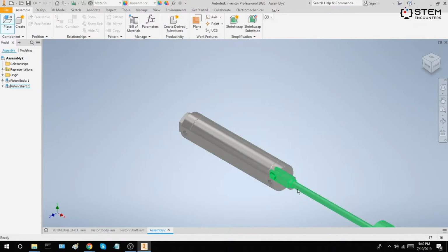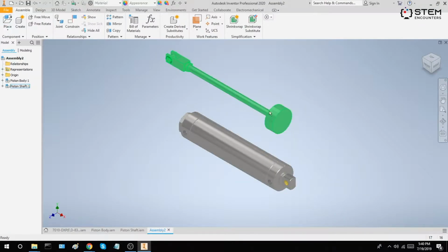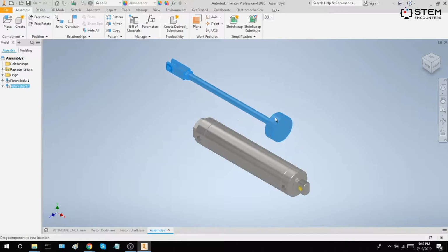This is because when you assemble the pistons and use a constraint to create the piston motion, you want that to be available within the file where your entire mechanism is being put together. This gives your mechanism some visual realism in that the pistons can move around with your entire mechanism.